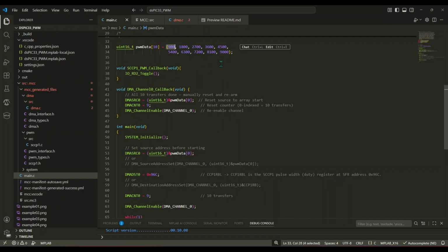So the 100% duty cycle exists for less than one full PWM period, too short to be clearly visible as a separate step on the logic analyzer. This is a direct result of the DMA reload and callback happening at the PWM period boundary. The reset is so fast that the last value gets overwritten before it can be observed.